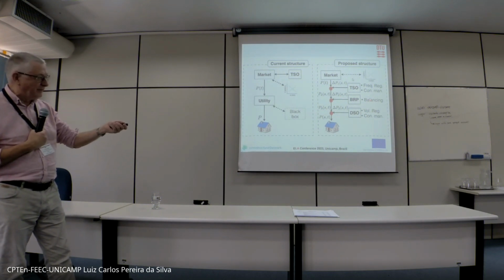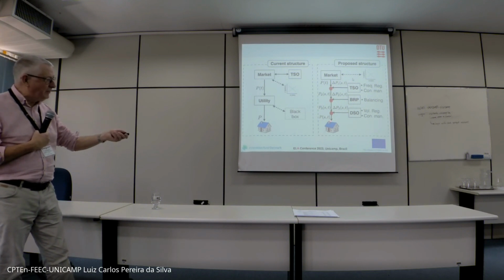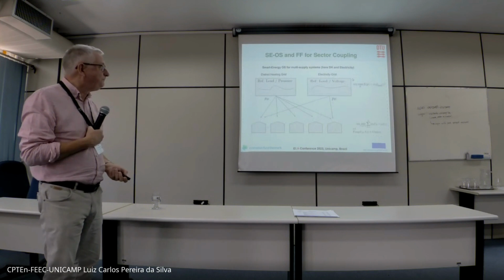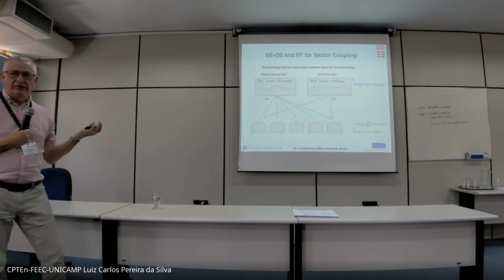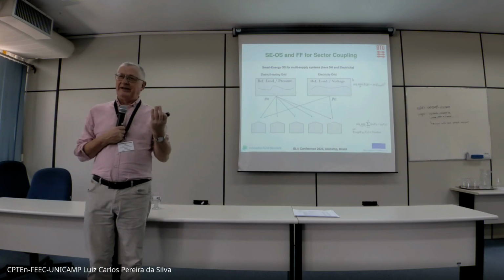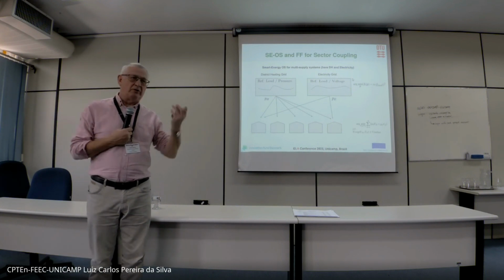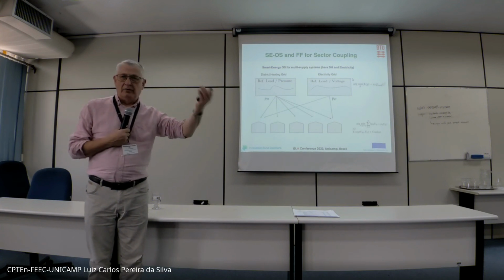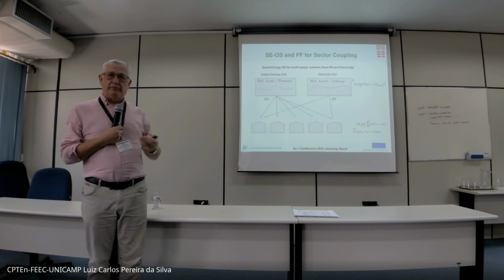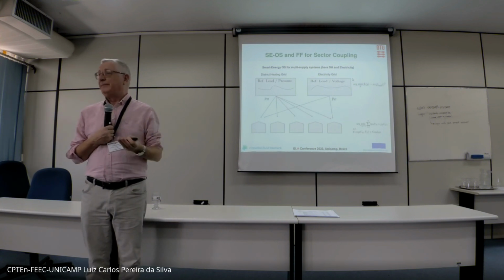We can also do the balancing, and we can have an aggregator which bids into the high-level markets and saves extra money. So each control problem here is a part of the hierarchy, and they create a part of the price, and the final price which enters the house is a combination of all these prices. That's why I say we have a hierarchy of controllers. The one problem with existing market things is that it's difficult to bid in the flexibility on different types of markets. Today in power systems, you have one market for the ramping, one market for the TSO for keeping the frequency, another market. So which market to bid into? That's ridiculous. But with this concept, we can just offer the flexibility to whoever wants or needs the flexibility.